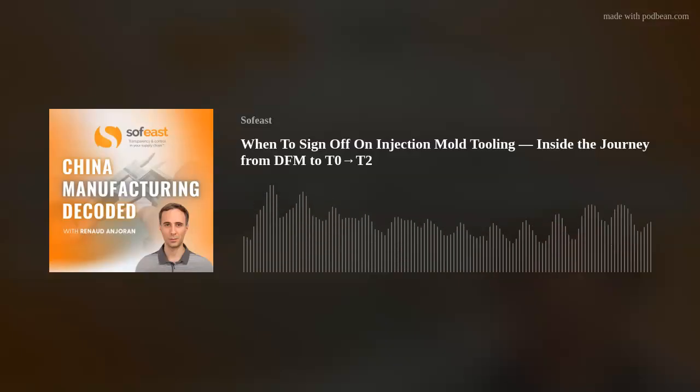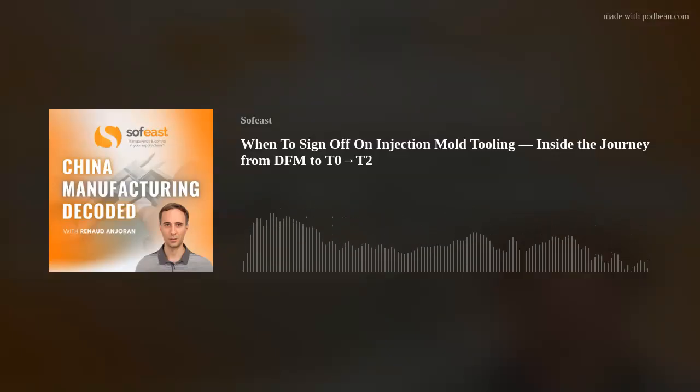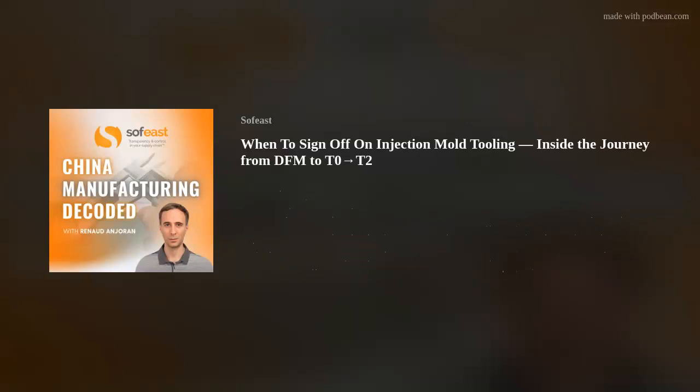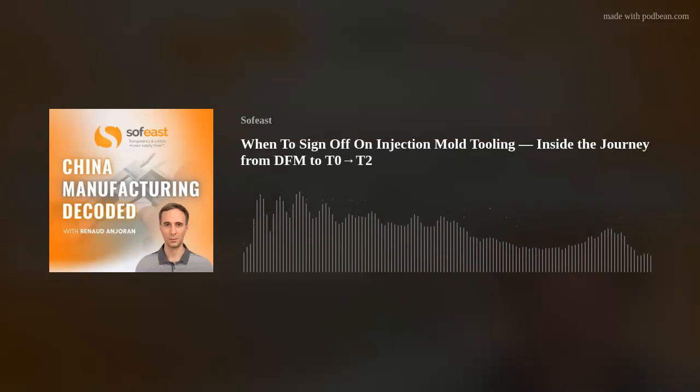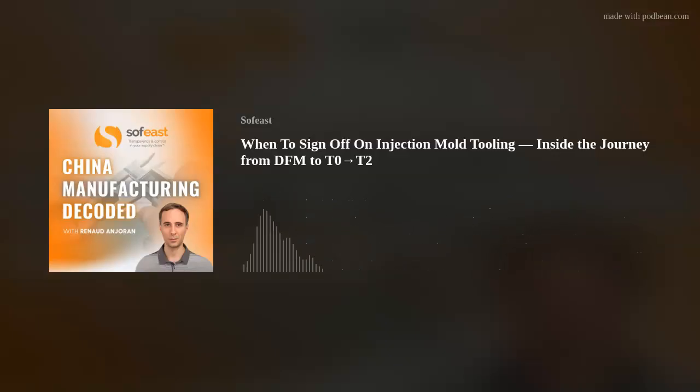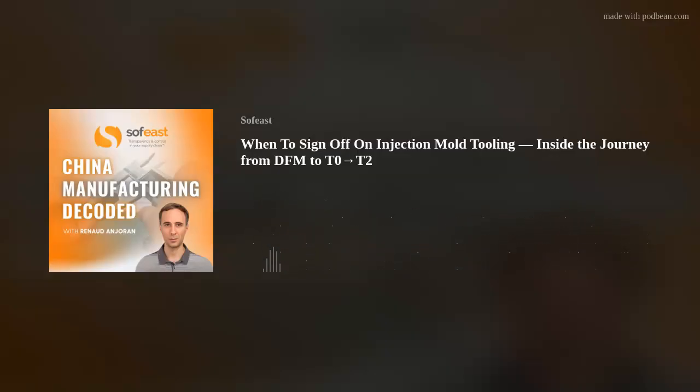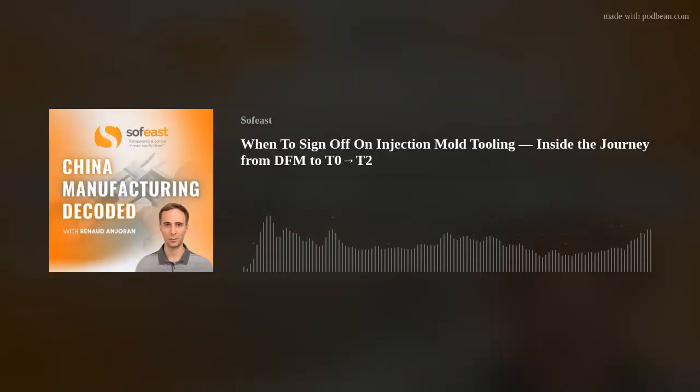Now, we know there are going to be some dimensional errors because we've made the tool what we call steel or metal safe. So where we know that we're potentially going to be tweaking dimensions, getting some dimensions into tolerance, this is where we take the tool out of the machine. We make those adjustments, and some of these could be big adjustments, by the way.